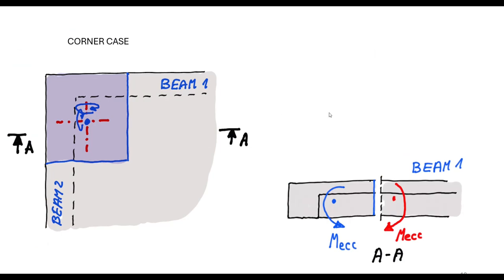In the case of a corner, we are assuming that our corner area is loaded in its gravity center with resultant point loads and resultant bending moments in direction X and direction Y. But in this case, to our corner, we have adjacent beams, beam 1 and beam 2, and those beams are much stiffer than adjacent slabs, so we assume that those beams will resist additional eccentricity moments.